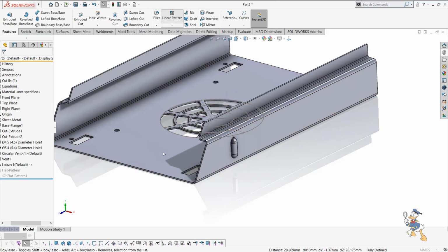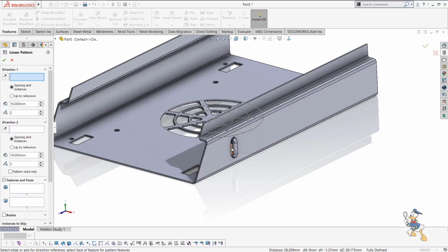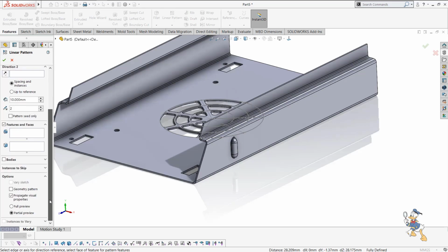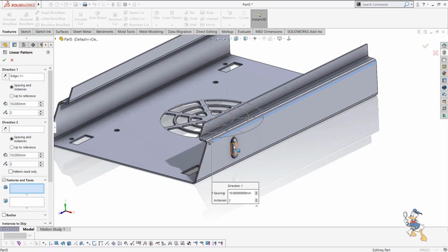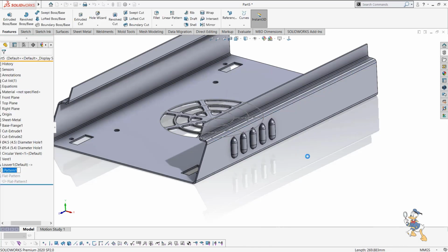So if we are focusing on how to make our tools in SolidWorks or in design software, it is a very time-consuming process. SolidWorks reduces our time because it is very user-friendly software, and we just need to provide the details in a very simple manner. Like, I just need to generate some louvers over here with a pattern distance of 15 mm, and then I just need to check it out. It is very simple to generate this kind of stuff in SolidWorks.